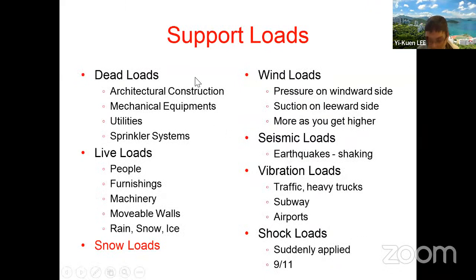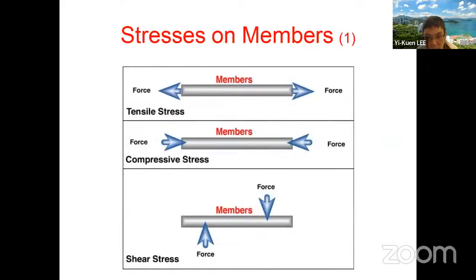And of course, in terms of building, as mentioned last time, we have classified the building loads in terms of dead load, live load, snow load, wind, seismic, vibration, and shock load. As mentioned, shock load has become quite important recently, after 9/11 in the United States. We'll also quickly show you about this issue.